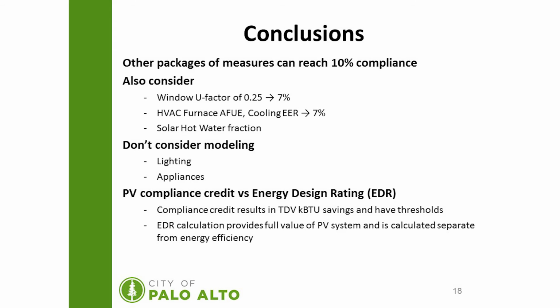A last note is that for 2016, the PV compliance credit that I just went over is not guaranteed to be available in later versions of Title 24. The compliance credit results in TDV kBTU savings and has a maximum threshold as we described. In 2016, there's also the energy design rating.